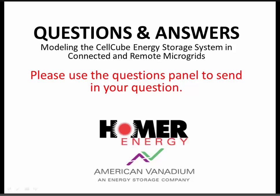If you're feeding a constant load, then by definition your current is going to increase. And since losses are proportional to I squared, the square of the current, you would expect your losses to be much higher at zero state of charge than at, let's say, 90% state of charge.